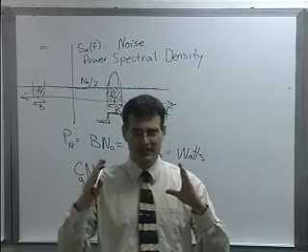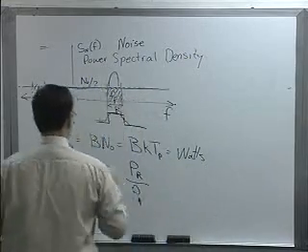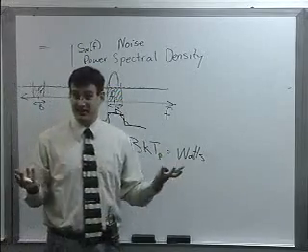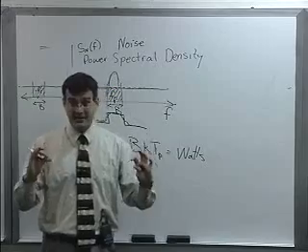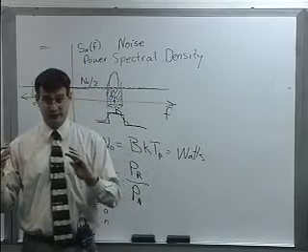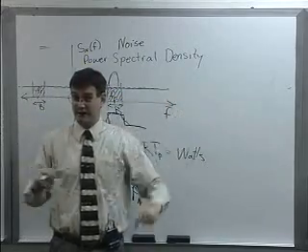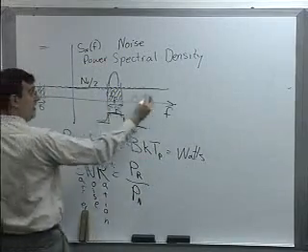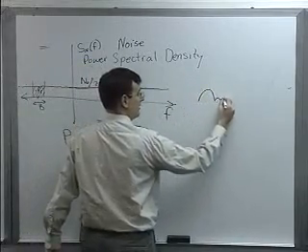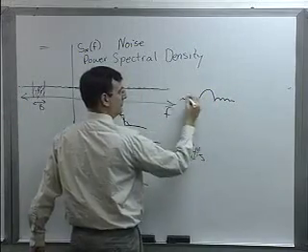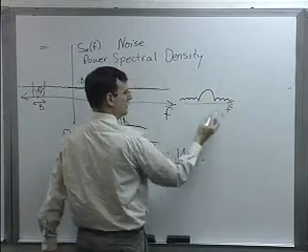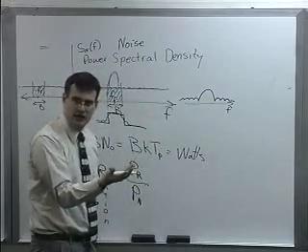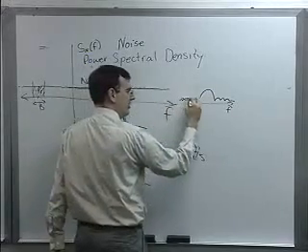And that just means that I've got a filter response that this noise has to pass through. And as soon as you pass additive white Gaussian noise through a filter, it no longer has a straight line for its power spectral density. The power spectral density of the noise will take on the characteristic of the filter. It'll ripple as a function of frequency. And so how do you calculate the area or the wattage? You integrate the area under the curve.